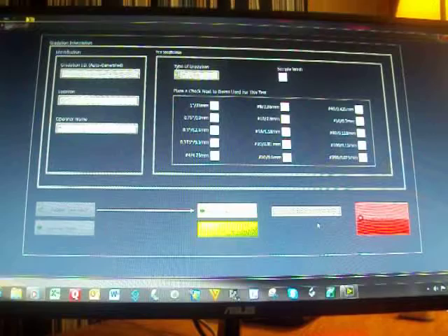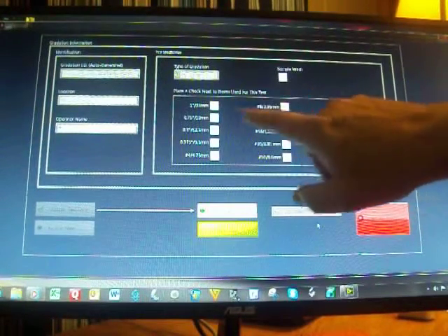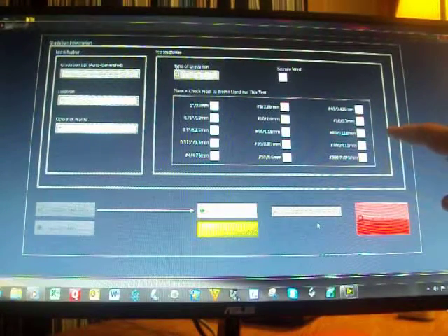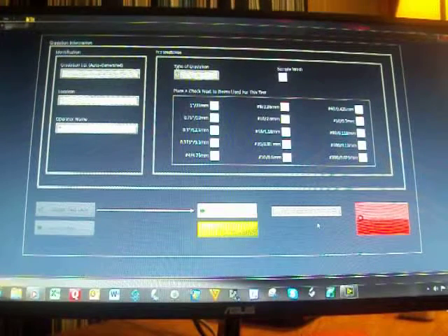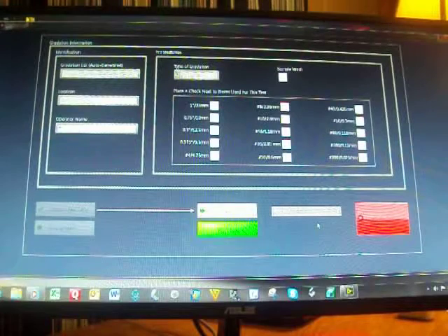And I'm sorry, what was that about the sieves? How you can choose certain sieves and what happens with the data. Oh, okay, sure. Although all sieves are available to be checked, if you don't check off certain sieves for a test, whatever weights are found on that sieve will be added to the next one below it that was checked for the test. So it's just as if that sieve never existed.